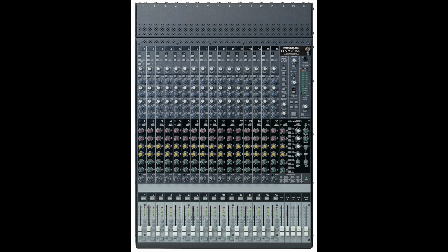Now below the phantom power, this is the filter. This is the high pass filter. It will let the high frequencies go through while eliminating all the low frequencies. The standard high pass filter of an analog console is around 80 Hz. On some analog mixers, it may have a different frequency. But what is most important is that the frequency of the high pass filter is already predetermined. So that means in an analog console or analog mixer, there's no flexibility for you to change the frequency of the